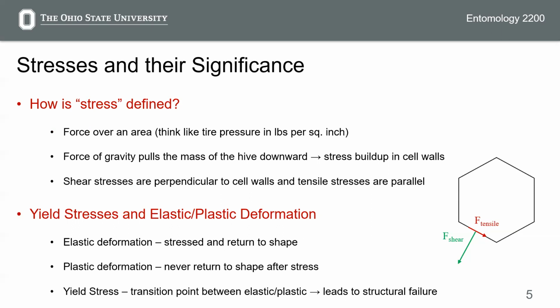of the applied stress. Elastic deformation is generally okay because this is usually reversible and non-damaging to the actual structure. Plastic deformation, on the other hand, which occurs once a particular value called the yield stress is surpassed, is bad and usually leads to structural failure.